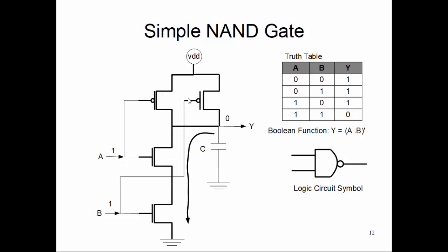Now why are they parallel? That is an electrical question. They also have certain relations between them about the sizes and so on, but for this class it doesn't matter. Just take it as granted. These two PMOS are in parallel and stacked over the NMOS stack, which is serially connected on top of each other. And each of the PMOS gates is connected to the A and B terminals.